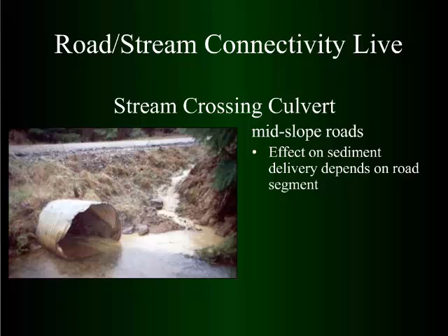Okay, this road obviously is right in the valley bottom. Mid-slope roads obviously can still deliver sediment, but at least you don't have the proximity issue. You have more of a chance of dispersing the water before it actually reaches a stream from a ditch on a mid-slope road versus a valley bottom road. Once again, the perception of people: they see a road that's down low, they assume, many times rightfully, but not always so, that it's causing sediment load problems.